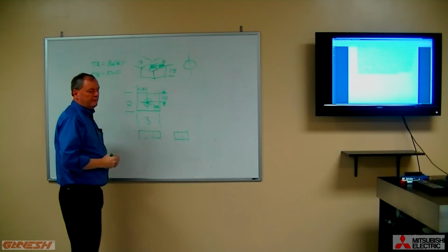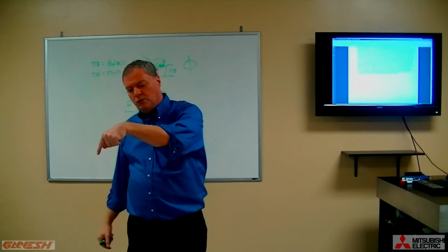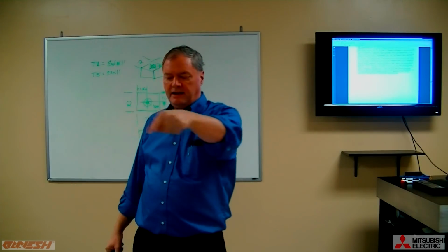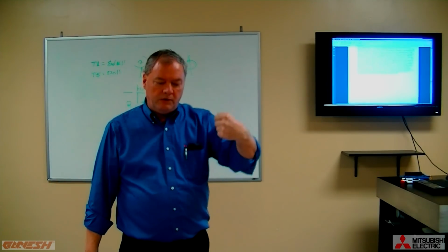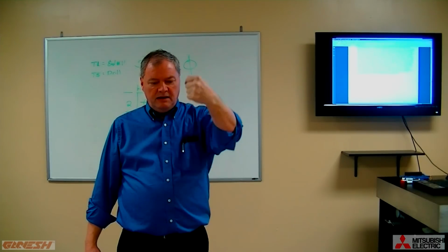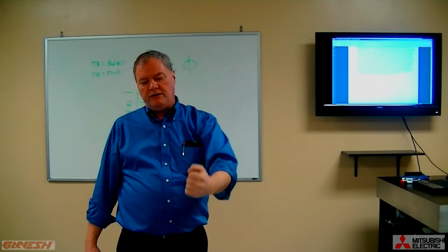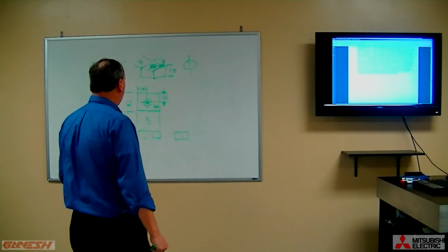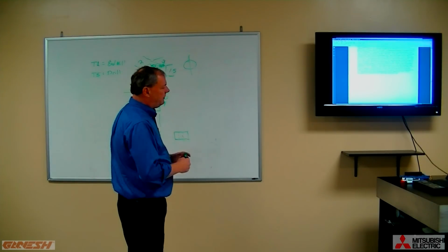Now you remember from our discussion the difference between end milling, which involves moving a tool around the profile in X and Y, versus single point operations like drilling, where we're simply moving to an X and Y location and then manipulating the Z-axis to drill a hole using a drill. So what would the part program look like for this?